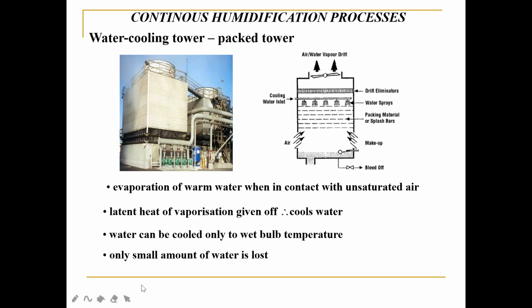Actually, a cooling tower works using the concept of evaporation. When you evaporate the warm water, and the warm water comes into contact with unsaturated air, there will be latent heat of vaporization given off, and this will cool the water in the cooling tower.